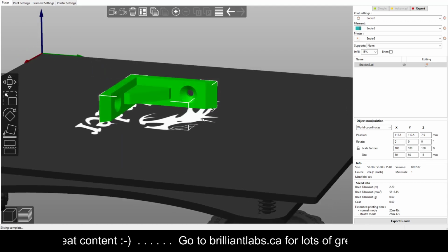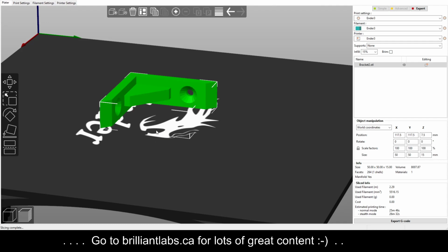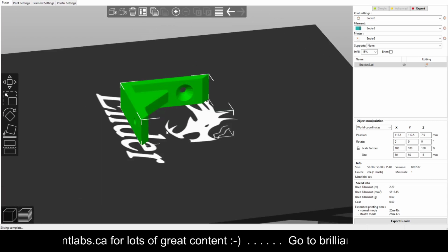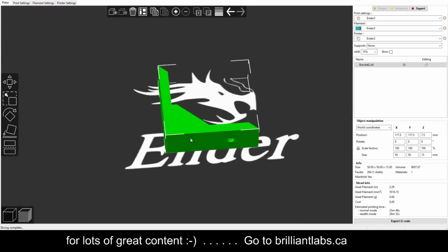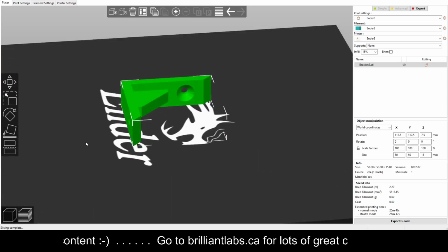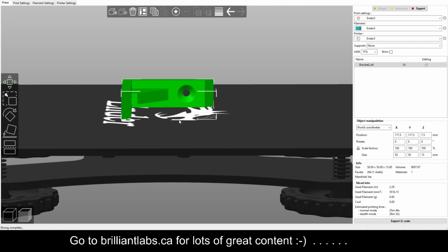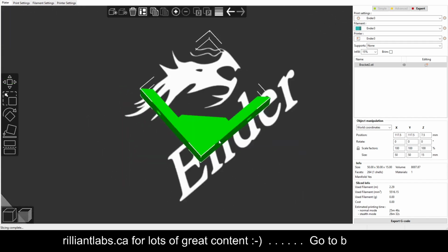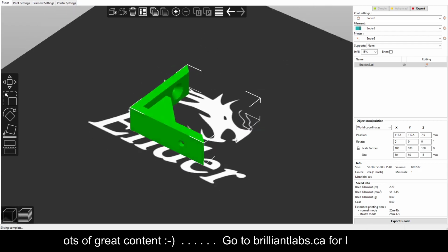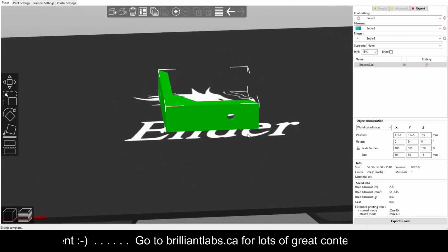There's a part in here that's not sitting on a bed, but yet it might cause a problem, 3D printing. But believe it or not, for those who've done some 3D printing before, this will print okay. Your printer will bridge across this enough to get it done. But if that were just freestanding, it would be an issue. But we should be able to print that one, no problem.